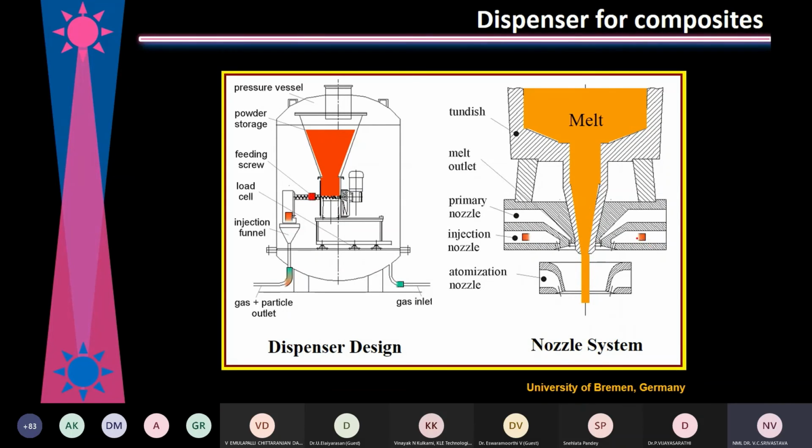So what is happening is that the powders and the gas go into the atomization zone along with the liquid. And any issue of agglomeration will not be there, and any droplet generated here will interact with the particles of the powders coming here, a ceramic particle for example, and they mix in this zone easily, giving rise to uniform distribution of particles in the matrix.